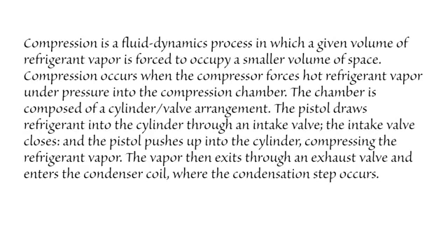Compression is a fluid dynamics process in which a given volume of refrigerant vapor is forced to occupy a smaller volume of space. Compression occurs when the compressor forces hot refrigerant vapor under pressure into the compression chamber. The chamber is composed of a cylinder and valve arrangement. The piston draws refrigerant into the cylinder through an intake valve, the intake valve closes, and the piston pushes up into the cylinder, compressing the refrigerant vapor. The vapor then exits through an exhaust valve and enters the condenser coil, where the condensation step occurs.